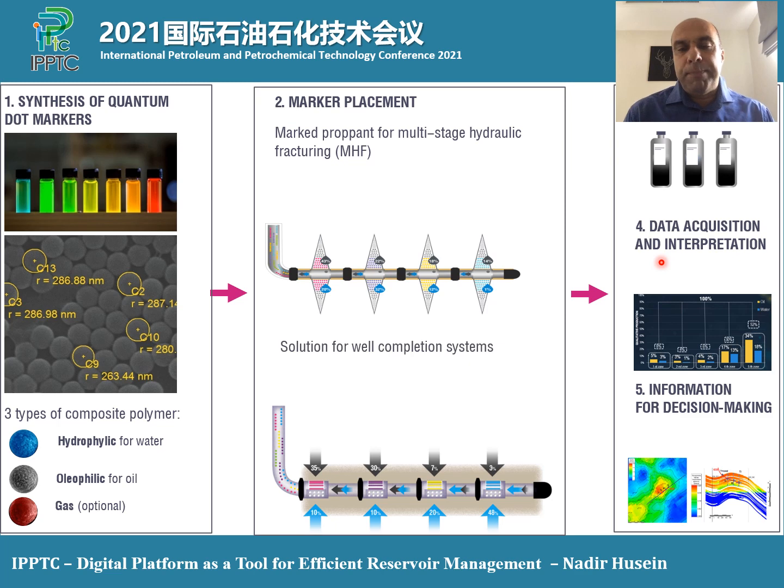The sampling on surface for liquid phases, meaning oil and water, is a quite simple process and requires taking samples on a wellhead, where the gas sampling is a bit more complex, where there is a need for a bypass line, and there are specially made mesh size filters to be able to capture the gas traces.